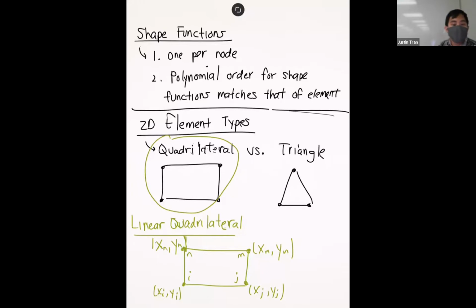Yeah. So if you have a mesh that's made of linear quadrilateral elements, do you know for a fact that the number of nodes you have will always be 4n, where n is the number of elements? It's going to be less than that, because each element is going to share nodes with its neighbor. The exact ratio is going to depend on the geometry, because one node might be shared by anywhere between 2, 3, or 4 elements. Gotcha.